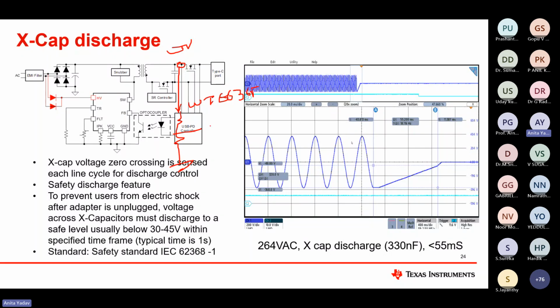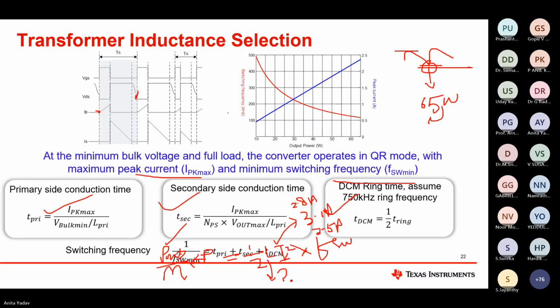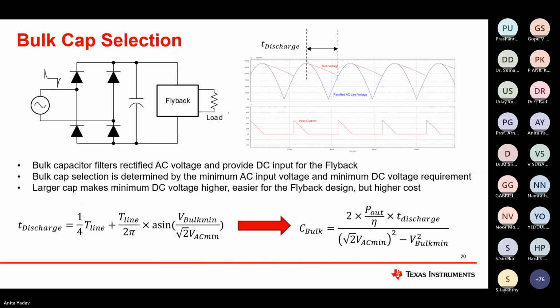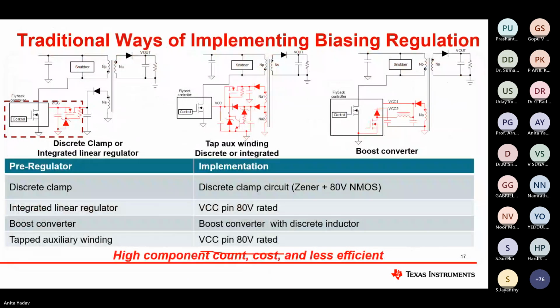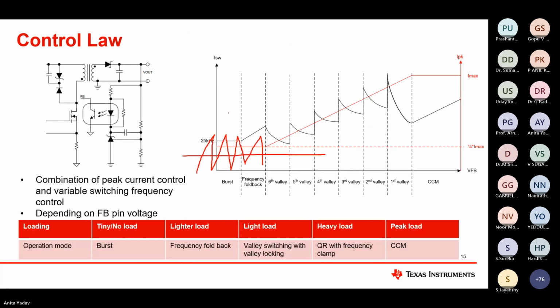So what happens here? If I go to this slide, the same circuit here, we are seeing the secondary side regulated compensation is using TL431, right?